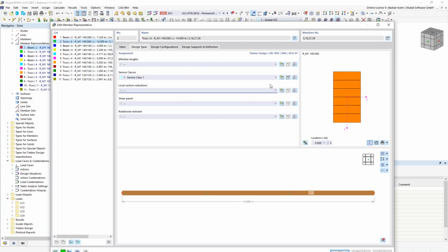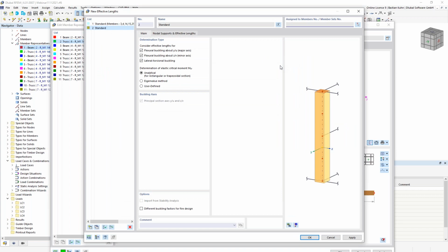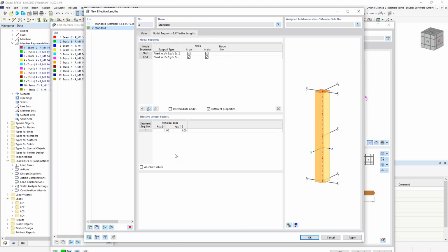Buckling, of course, also for the bottom girder, this is probably relevant, but maybe not. Well, we could also do it for lateral torsional buckling, but as the load is introduced at the top of the top girder, it's maybe not so relevant in here. And here as well, for the buckling, we can try to design a little bit more efficiently and say it's held in the stronger axis by the stiffening elements, and for the other direction I can choose the whole length of the beam, which is of course 40 meters.